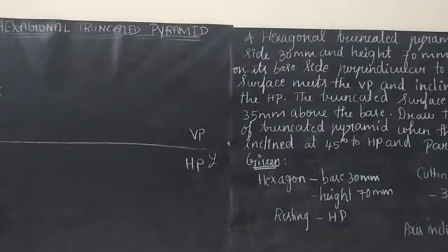Actually, after drawing the cutting points, we will be getting the sectional top view, right? So see here, this 1 dash 6 dash, when you try to draw vertically downwards, 1 dash is lying between O dash and B dash, so within OB we will be getting 1, and 6 dash is lying between O and A, so within O and A we will be getting 6. It's very easy to get.